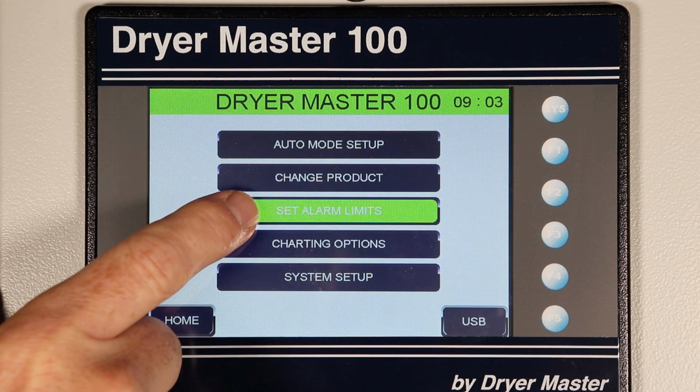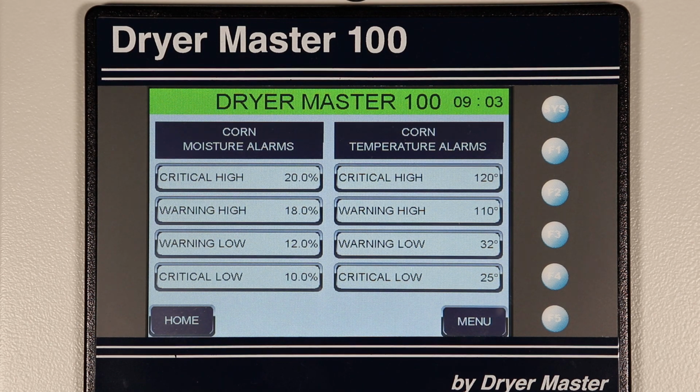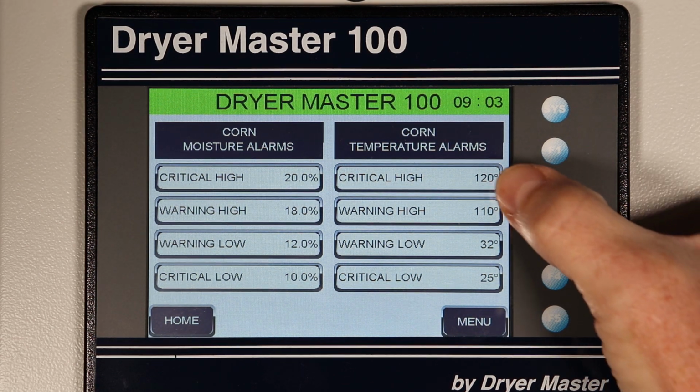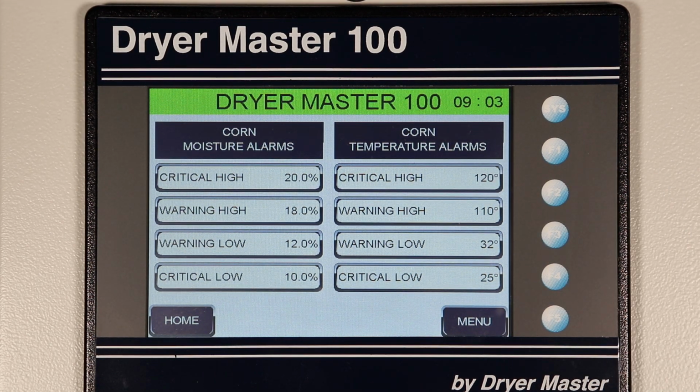We can set alarm limits. So before we saw that once the temperature got over 120 degrees, we set off a flashing alarm. So this is where you can set your alarm limits, and some people set them very tight, some people set them a little bit looser. It's all a matter of how you want to be notified if something is unexpected. So you have ideas of what ranges things should happen in, and if they go outside those ranges, you'd like to hear an alarm. Okay?